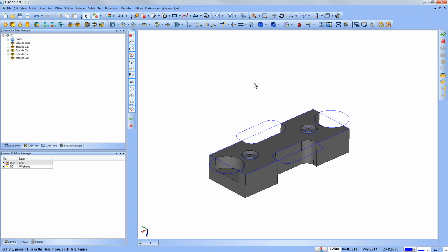Nothing changes on the screen until you see me toggle this layer, right? So there it goes, right? So it's been sent to that layer. Just an organizational thing. I want to take a couple seconds to talk about that. Maybe most of you are familiar with that, but organization will keep your models and construction of your models clean. As I mentioned also earlier, having geometry that joins, that's free of gaps and duplicates, entities that have gaps, those are going to be problems for surfaces and solids. So you want to start from good geometry, and you will get good solids from that.